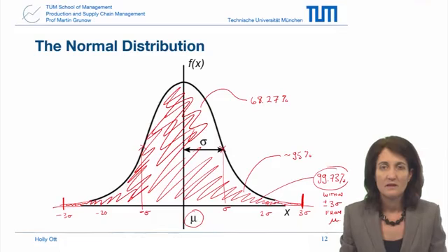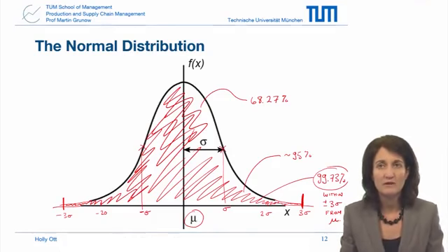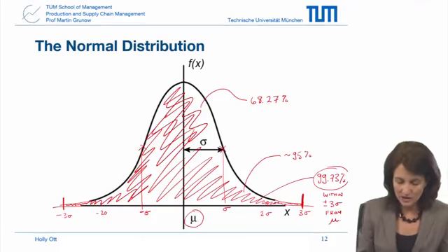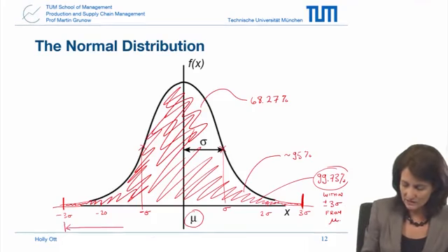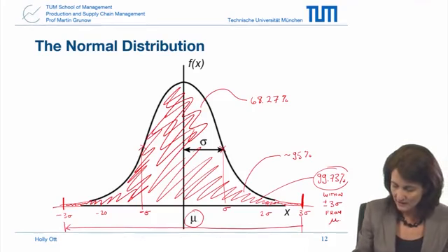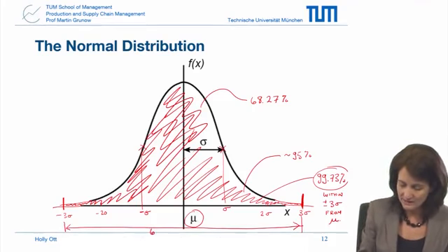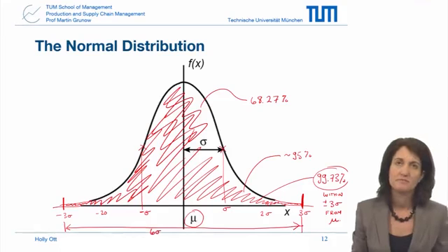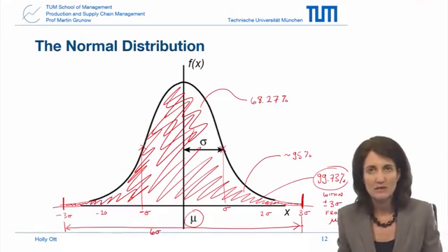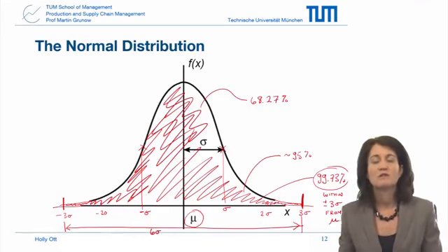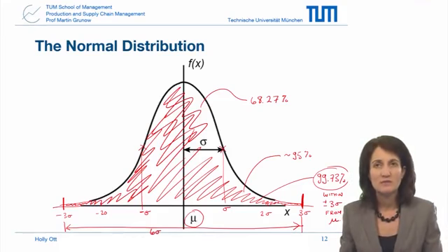So, this means that if a random variable is normally distributed, then almost all the data, 99.73% of the values, will be within 3 standard deviations of the mean, which is a total spread here of 6 sigma. And it's this 6 sigma that we will use now to express the process overall natural variability.